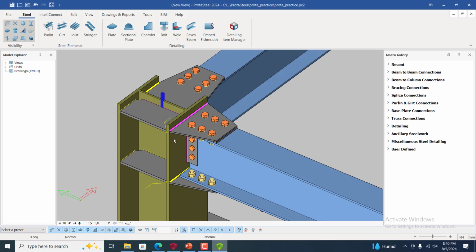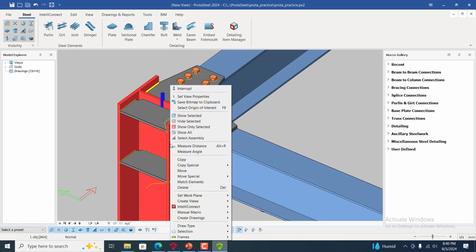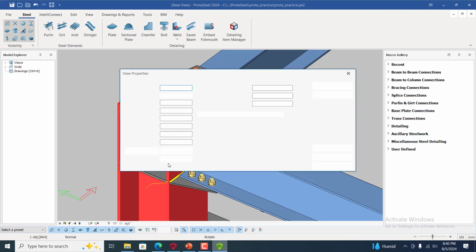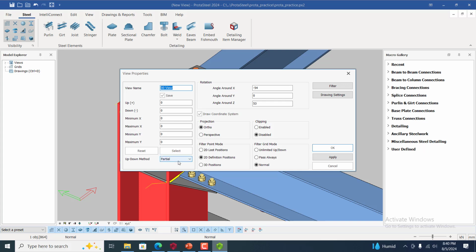One very interesting thing is that some of your structural members here, you can see by just right clicking, and when you click on the properties, you can as well use from these properties to rotate any of these members. Okay, you can rotate any of these members.